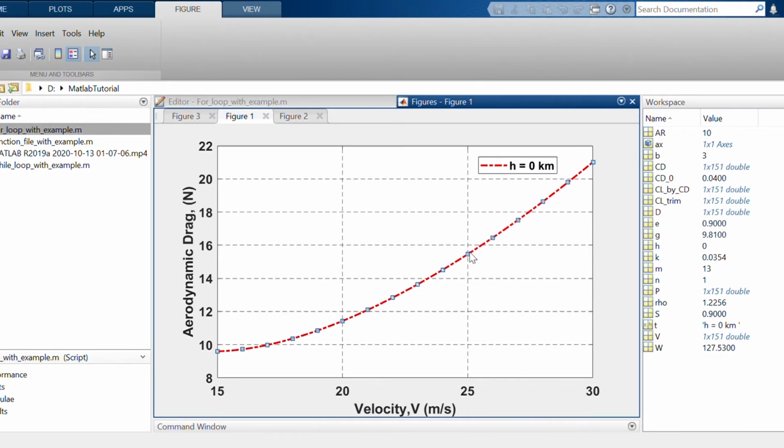Now you also have options like, suppose you have so many graphs, how will you differentiate? One way is by color, but if you want to print in black and white, then color will not matter. You have to differentiate by something else, like using a marker. We can go to the plus. You can reduce your marker size and you will get plus. Or you can go to hexagon, diamond, circle, so many options are available.